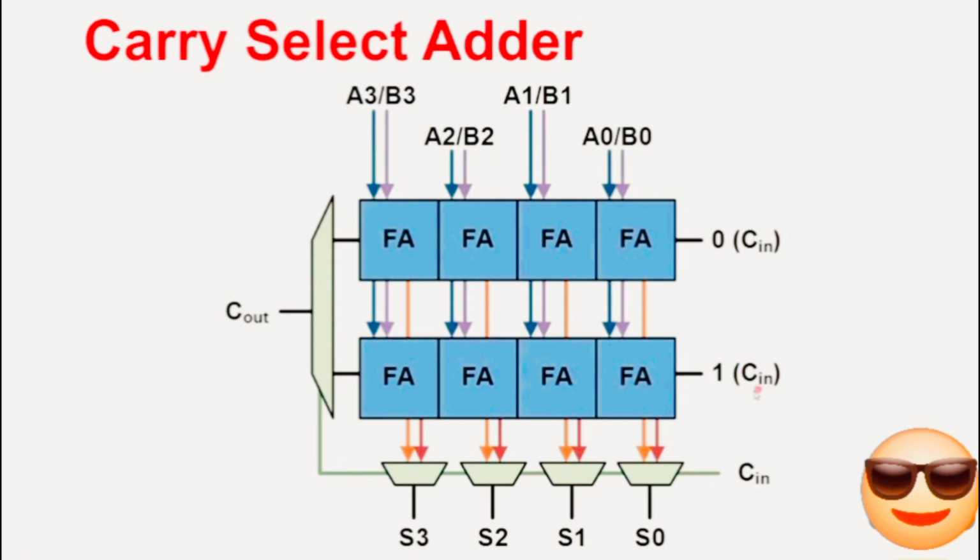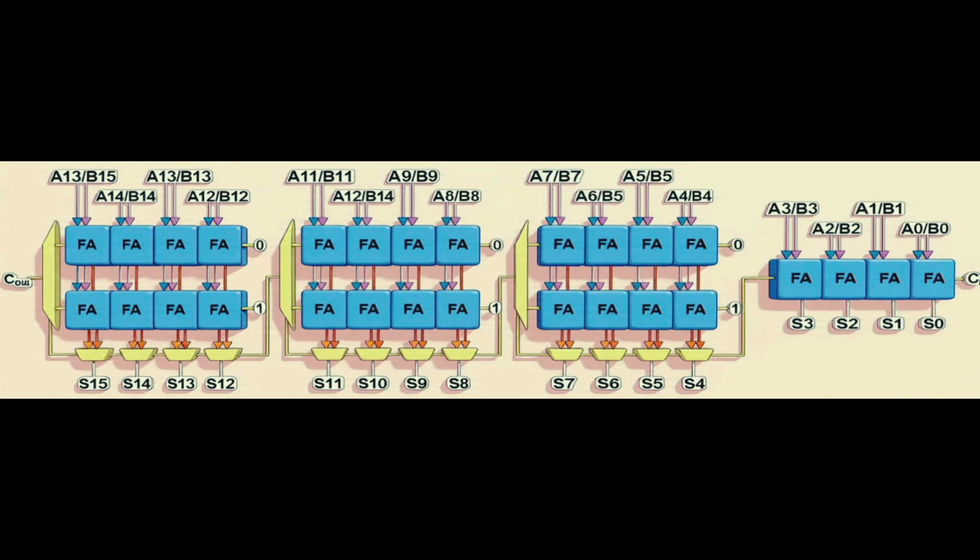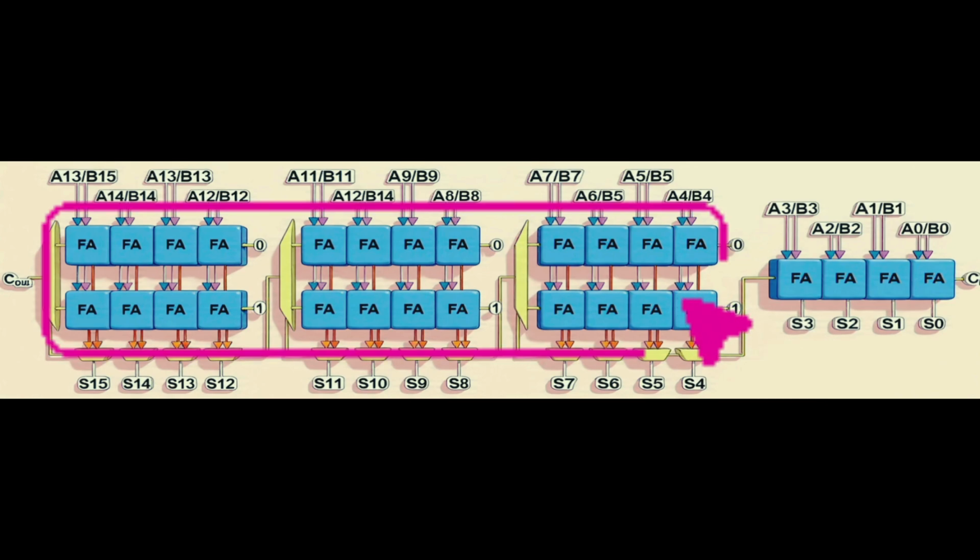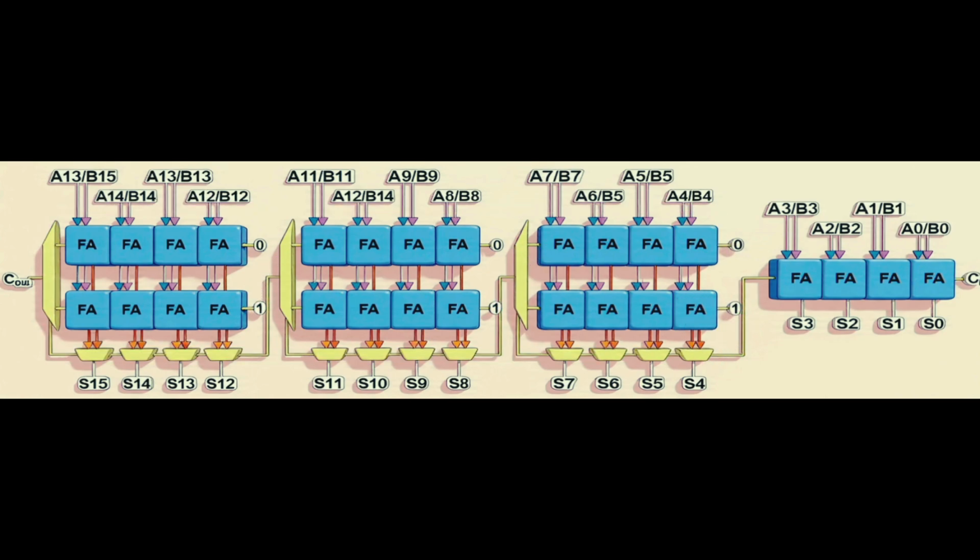The architecture shown here is a single 4-bit group. In practice, carry select adders are built by chaining multiple such groups to cover wider word widths. The carry output of one group's multiplexer becomes the actual carry input select line for the next group's multiplexers. Each group computes both its 0 carry and 1 carry results in parallel during the time the previous group's carry is propagating to it.